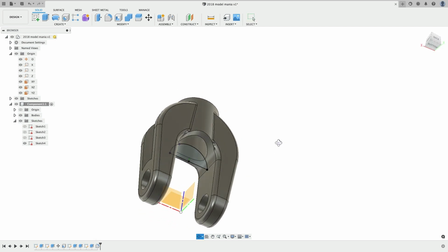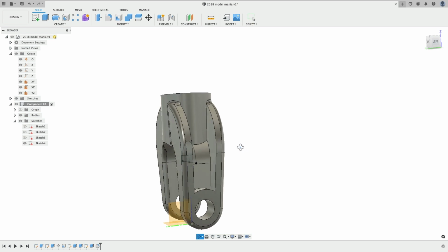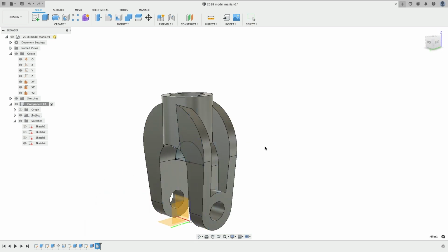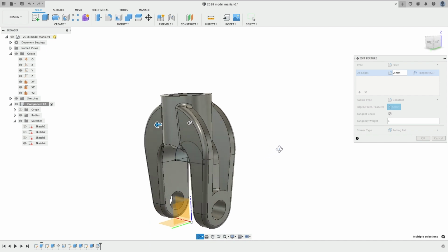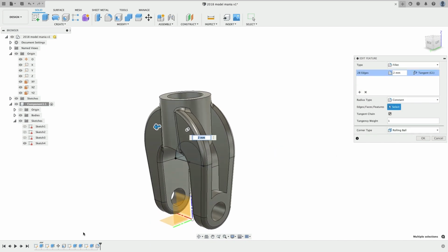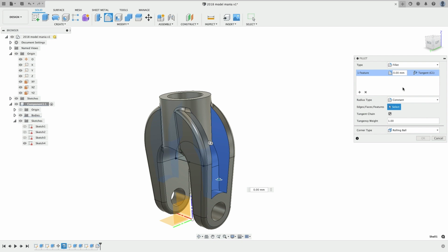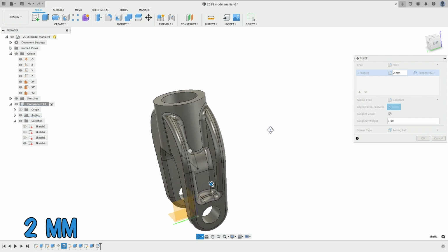Still solving for the most part, but some are missing and some of these interiors are missing. Next, let's edit the fillet that's missing some edges, these new edges. And in SolidWorks, there's a cool way of just selecting a feature, like selecting the shell. So if you select it and then add, let's do a new fillet, select the shell, add a fillet of 2 millimeters, is it going to let us fillet that new shell feature? It does. It's pretty exciting.